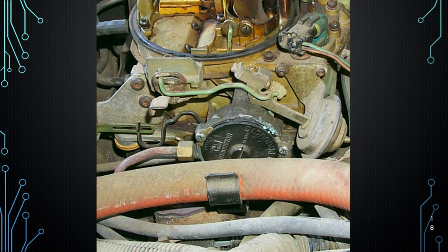The image alone is hard to definitively tell if the engine is running. Typically, if the choke pull-off rod is retracted and the choke plate is partially open, it suggests the engine has vacuum and may be running or was recently, but without a direct view of moving components like belts or sound. It's not absolute. Visual cues alone can't confirm it 100%.